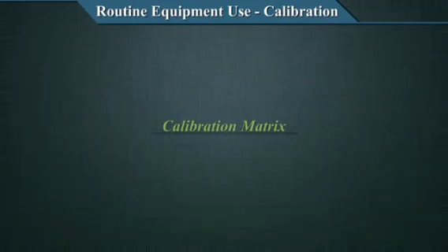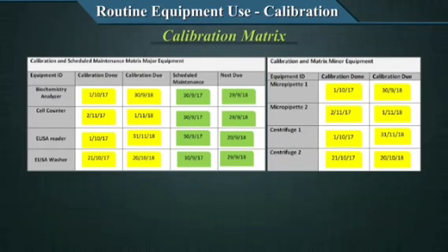Now that we have understood some basic concepts in calibration like traceability, uncertainty, frequency of calibration, how we can have calibration of minor equipment and ancillary equipment and major analytical equipment, who will do the calibration and how frequently, we have to come back to the documentation again. Documentation of calibration is very, very important. We already talked about the information sheet for calibrations.